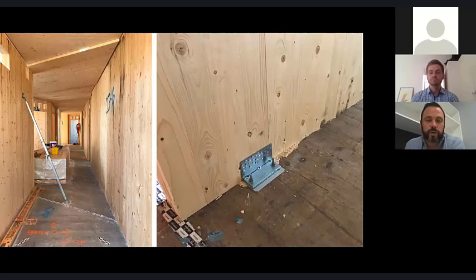Now, we didn't want to spend too much time talking about acoustics. There's a slide at the end, but acoustics and fire are really important, because you've got to build your floor up for acoustics, you've got to have a ceiling for acoustics, you've got to fire rate the plasterboard, and you're going to have a false wall in front of these walls for all your acoustics around all your hotel style design. Coordinating these bracket designs into those finishes from an architectural and engineering perspective is really critical. I've seen jobs around the country where brackets are left exposed and the floor covering only covers part of it. You can see it, and I just don't feel like it's the best outcome.